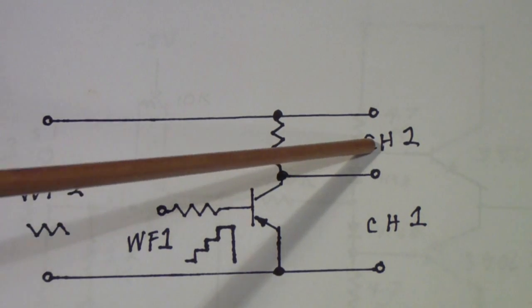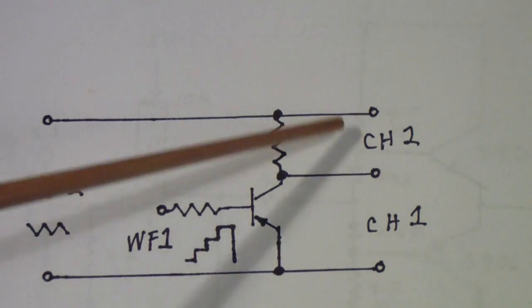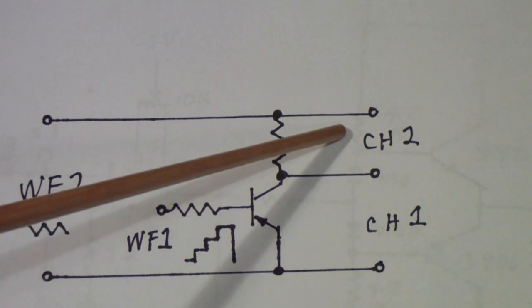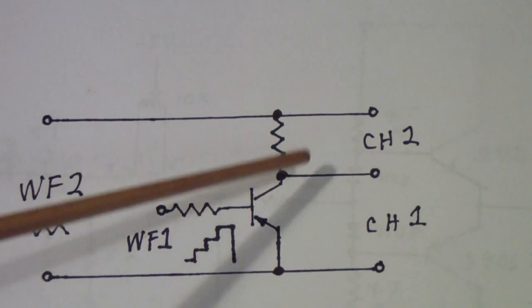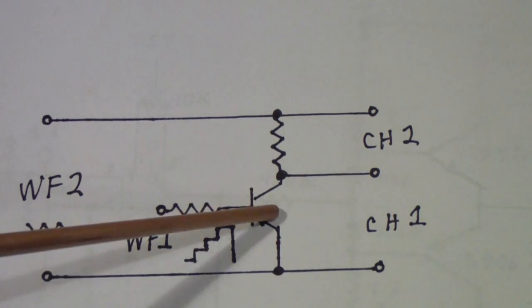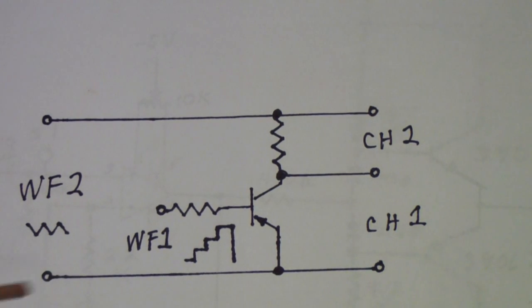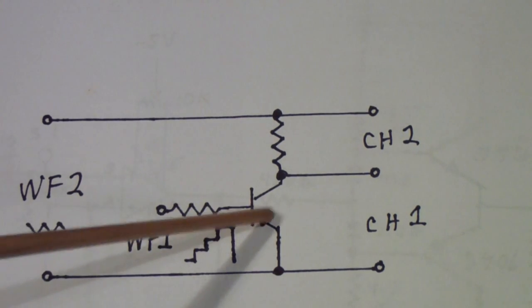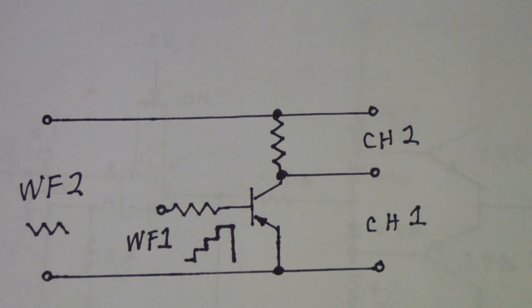But on the scopes, you could put a double pole, double throw switch here so that in one position it was configured for NPN transistors and in the other position for PNP transistors. Then you could go through your set of NPN transistors looking for the one that most closely matches the PNP of the same complementary pair.